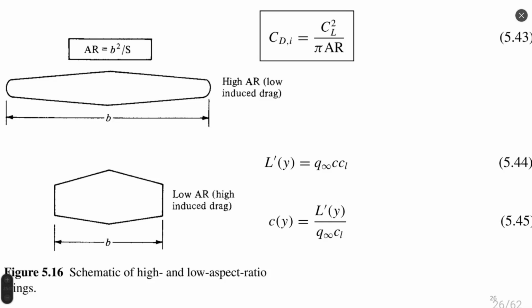Okay, but also do not forget about this numerator, CL squared. For example, you improve the lift coefficient a little, but your drag coefficient will also increase. Do not search for infinitely high values of lift coefficient. Very high lift coefficient values have several disadvantages. You always need to search for the balance between lift and drag.